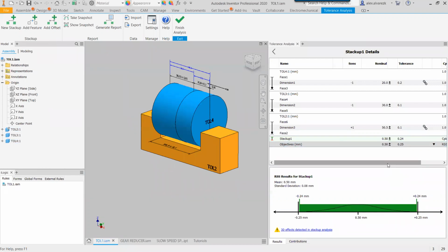A question from Kelly: would changing the nominal size have the same effect if the tolerances were left as originally started? Can this be changed through the analysis also? So you're asking if you can change the nominal. The nice thing about this tool is that it's completely built into the software, so if you change the nominal size, it will update your results here. Typically, if I were to manufacture a part, I'm always going to aim for the nominal.